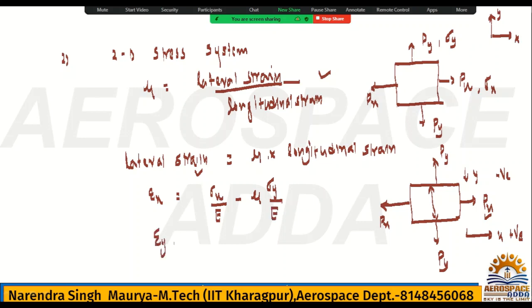Similarly, you write epsilon y, that is strain, because it's a 2D system, so obviously 2 strains will come. So now if you are talking about epsilon y, that means first you will take in y direction. In y direction, what is the load? It is py. So what will be the stretch? It will be sigma y divided by E. Because of the y load in y direction it will be positive strain, but in x direction it will be negative. Why? Because if this bar is elongated in y direction, then in x direction it will be shortened. You just think about it. Then it will be minus mu sigma x by E.